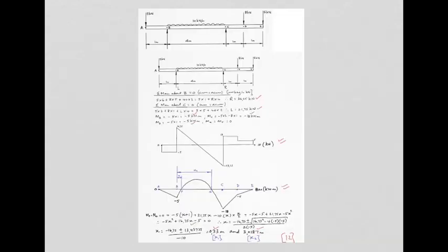In your solution, you will probably have noted that the maximum bending moment is hard to define unless you remember that it occurs in line with the point where shear force was 0. So that's a significant point to note. Also that the UDLs curve skywards, as we said, so they curve that way. And between this point and that point, the shear force diagram is sloping and the bending moment diagram is curved where there is UDL. Where there is not UDL, it is straight lines.